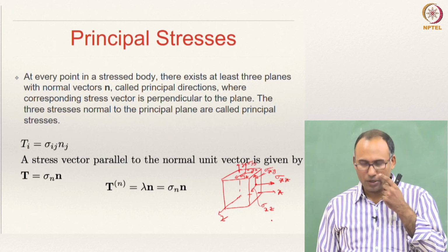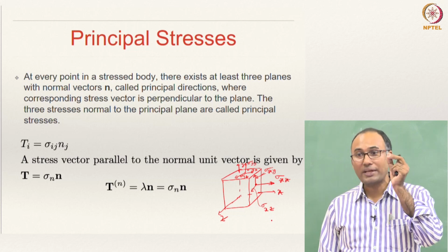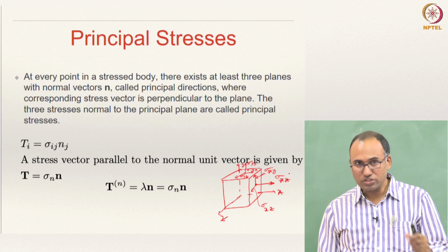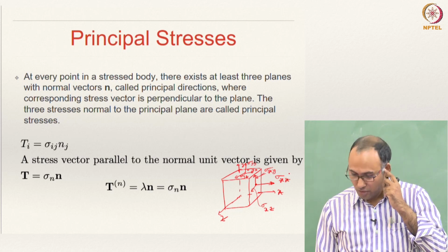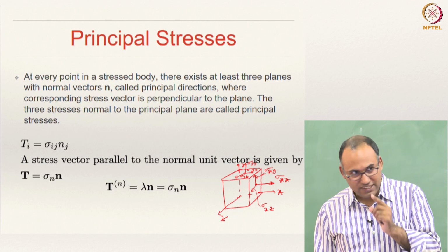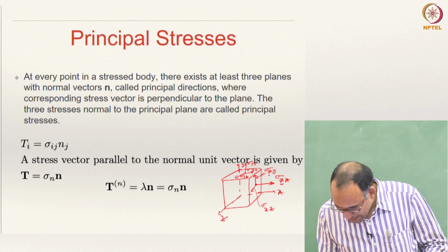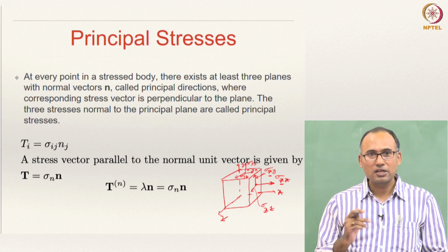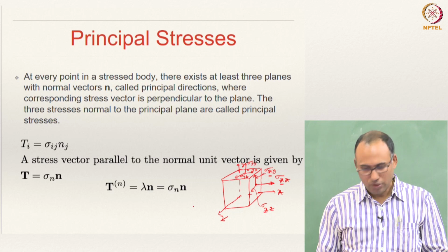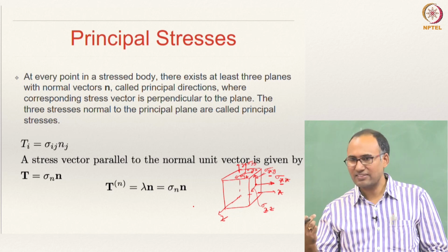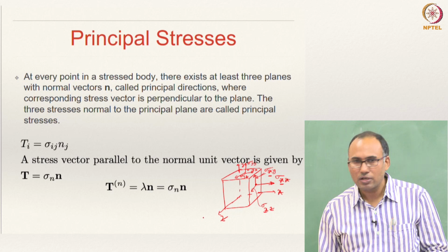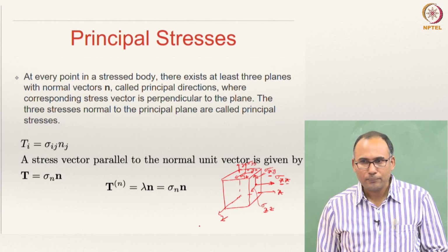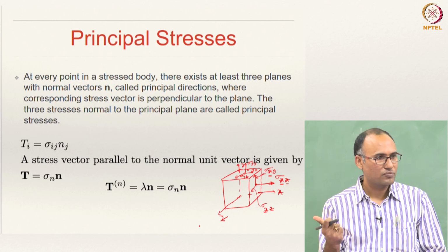And if you carefully observe, if you want to describe one element of this stress object, how many indices are you using? 2 indices. The first index, if you carefully observe, in all these represents the direction of the normal to the plane. What is the direction of the normal to the plane? X-axis. So, the first index represents the direction of the normal, and the second index represents the direction in which it is acting, right.